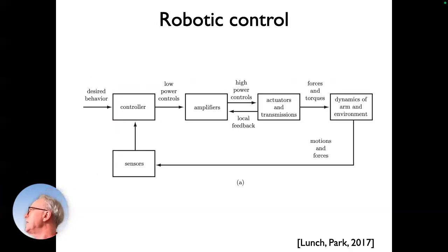So for the robot, more concretely, the actuators are typically just the motors. There are also robots that have more complex things, like transmissions or Getriebe, which we're not looking at here; we're just thinking about actuators. The device that controls those is something electrical, an amplifier kind of system. And in many of those systems there is another feedback loop, where you're correcting the action of the amplifier by measuring something mechanical about your motor, not yet about your arm. These are the servo motors.